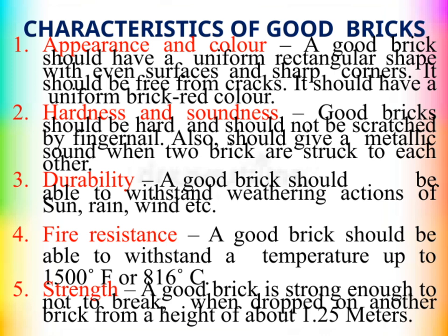Durability is crucial, too. A good brick should withstand the weathering effects of sun, rain, and wind over time without deteriorating. This ensures the structure built with such bricks remains strong and stable. Fire resistance is another key factor. A good brick can withstand high temperatures, up to 1500 degrees Fahrenheit, or about 816 degrees Celsius, without losing its integrity. This makes bricks suitable for fire-resistant structures and safety requirements.